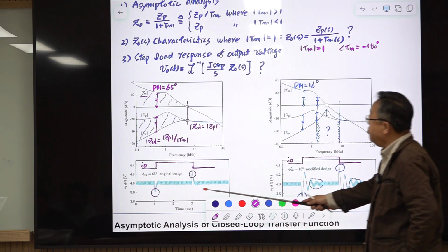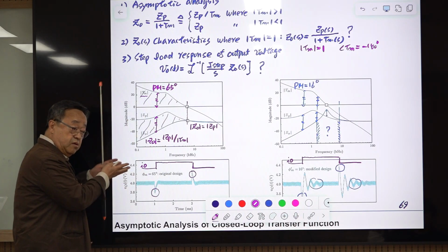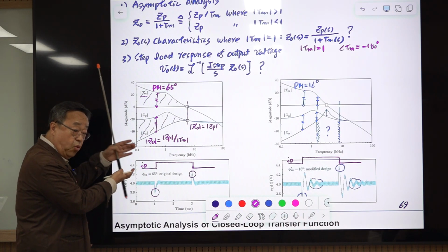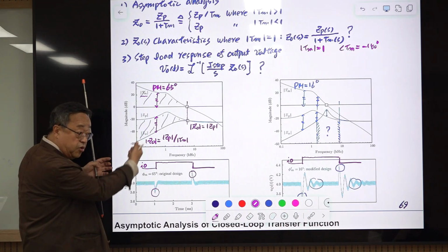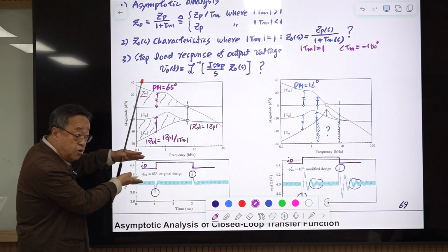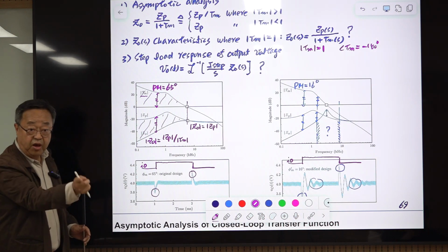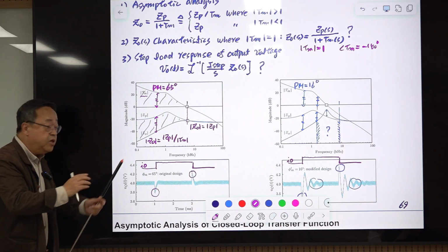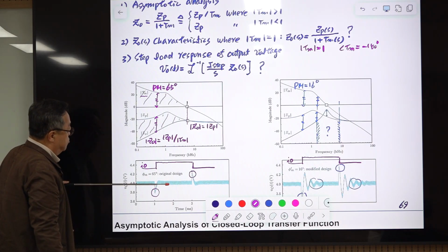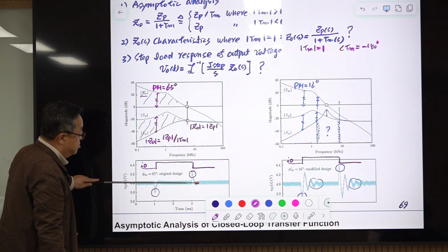So it goes down when this current steps up. Why is that? Our voltage is fixed, and load current is extracting more energy. Then temporarily, our capacitor voltage will be reduced. Okay, so it goes down, and later on, due to the action of the negative feedback, it's recovering. So we have here the undershoot, and for this case, overshoot.